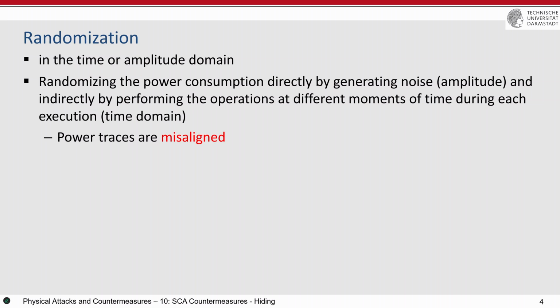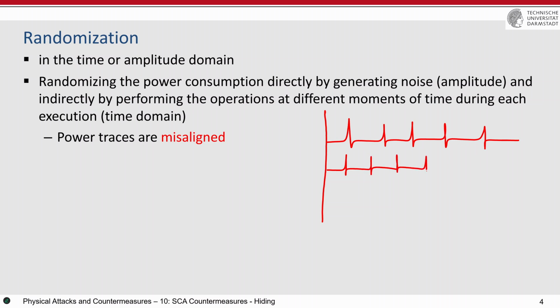But what is important, I think I explained this a couple of times, is that the power traces should be aligned. This is what you have learned. You have some power traces, different clock cycles. If the power traces are something like this, that they are not aligned, the next power trace is something like this, and so on. Then if you run the attack, DPA or CPA, on this, then this peak doesn't happen at the same time. They are not well aligned together.